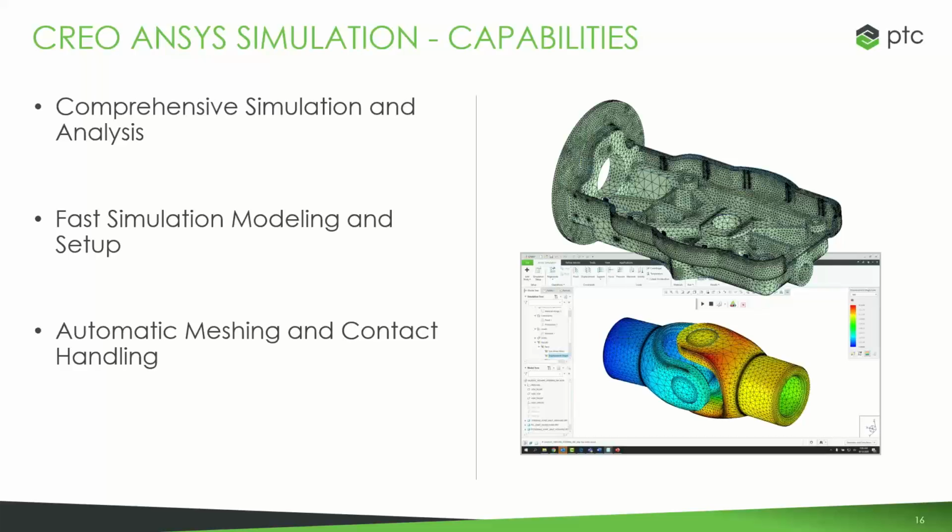And you do have more advanced options for controlling the mesh or refining it in certain areas that you want to focus on. And also handling contacts is done in the same way. You're able to have the system automatically detect contacts for you, but you still have the ability to manually define contacts as well.